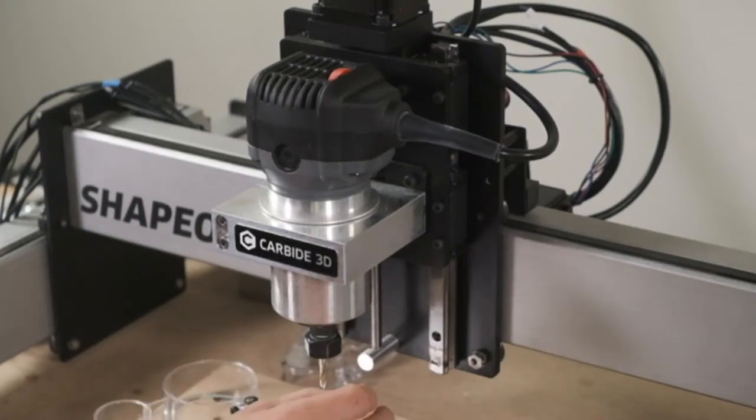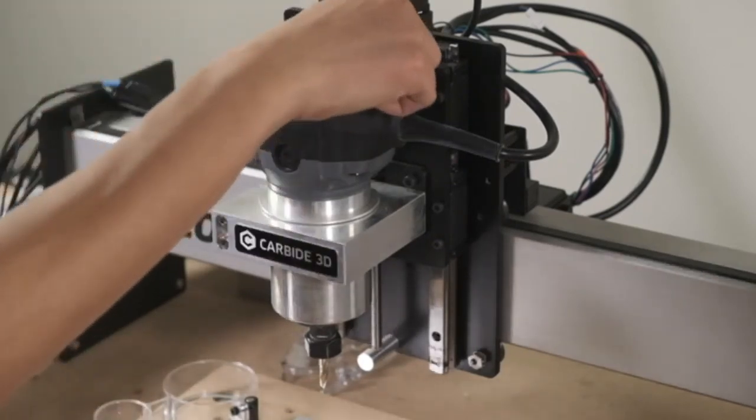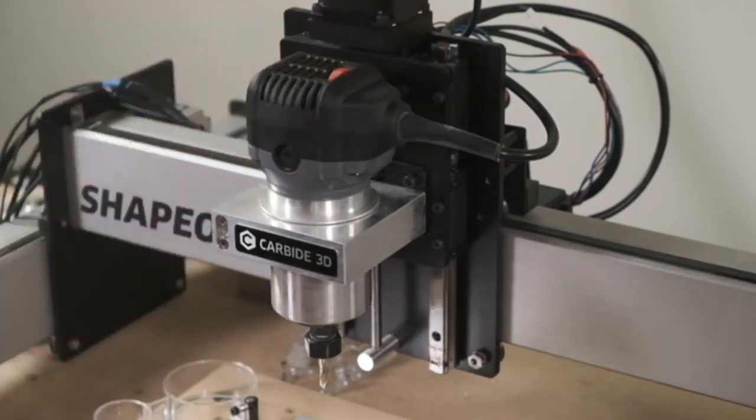Over time, as dust particles cling to these rails and get pushed off, they will wick away a little bit of that oil or grease. So eventually, depending on how heavily you use this, it could be years, it could be months, you'll want to take a little syringe, fill it with grease. There's a grease port on the tops of these blocks, and just inject some more grease into there.